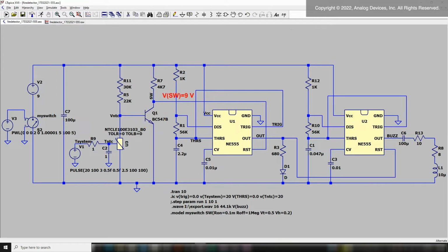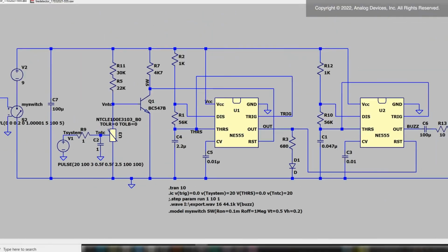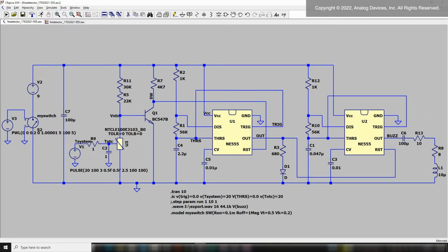is blocked. The 555 timer U1 is reset. Vout gives a pulse signal which will reset the second timer to produce a new pulse at another frequency. That's the siren noise. In fact, LTspice 17 allows to save voltage as sound files so we can hear it now during the video. So let's go for a simulation.